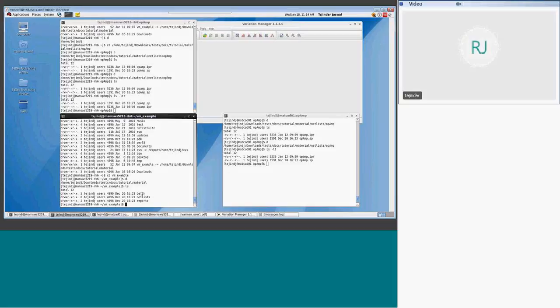But if you're doing high sigma, like if you're running 6 sigma, then the number of simulations is going to be increasing, right? The variability explorer is just to give you the full blown picture, for things like when the design is passing. For example, when you start the design, device parameters are not stable if you are running at low temperature or high voltage and other stuff like those.